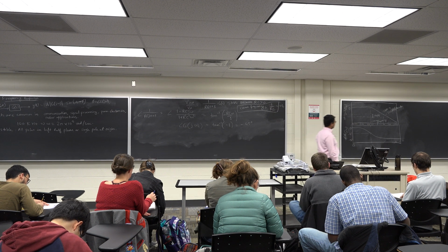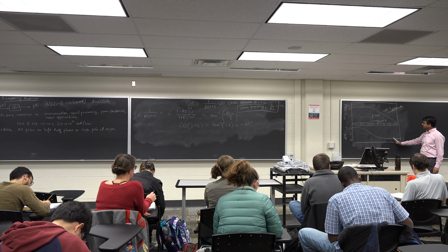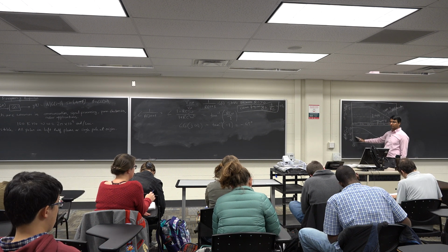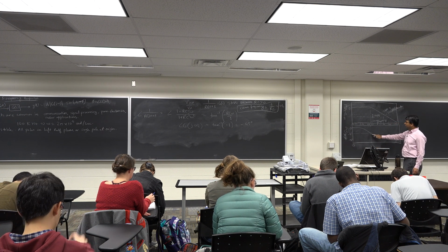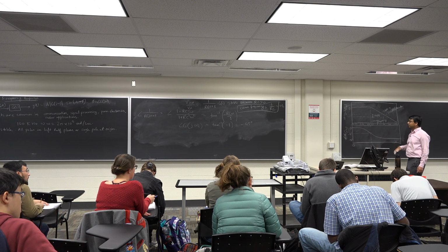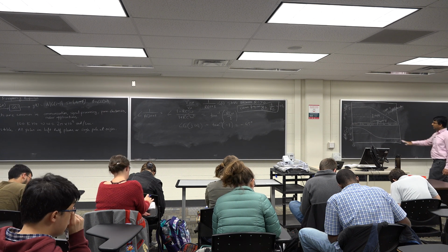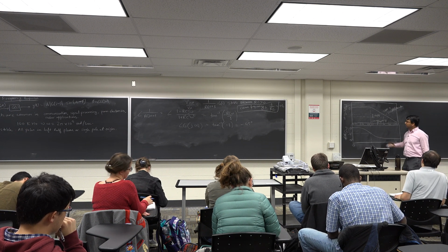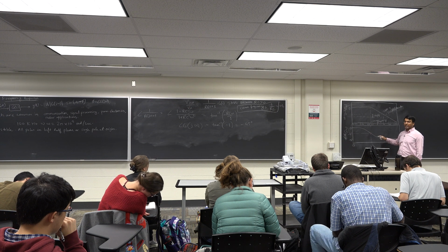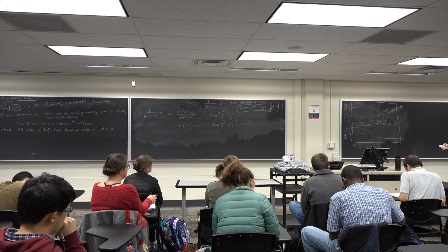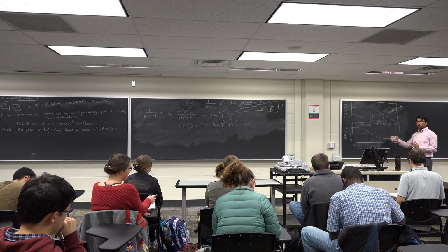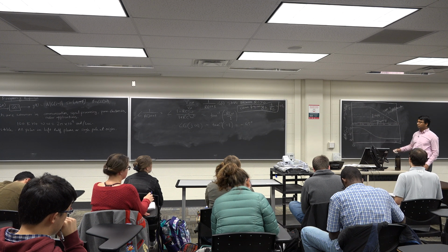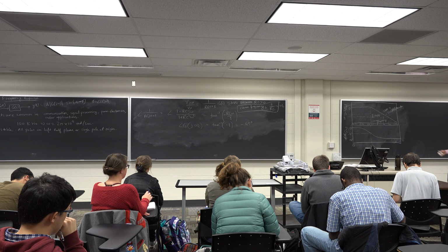All right. So we have figured out that there is a phase change of 90 degrees at very high frequencies. There is almost negligible phase change at low frequencies, and around the corner frequency there is a phase change of approximately 45 degrees. That is something we can read from this phase plot. Another important thing is that even the phase plot can be plotted using the input-output behavior of the system. You can look at the oscilloscope of the output and figure out what the phase difference is between the input and the output, and that will tell you what the phase of the system looks like.